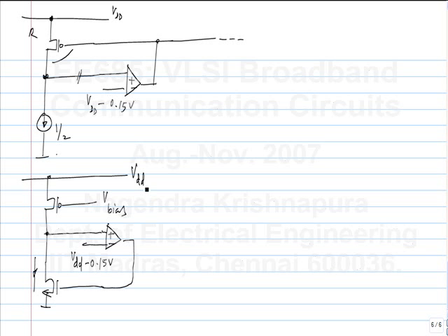So, basically you try to keep the swing constant, okay. You cannot control the I and R individually, but there is no need to control that perhaps. So, you try to keep the swing constant. Now, let us say there may be cases where I want to use a resistor, I do not want to use a PMOS transistor, and that could be because generally transistors can have more parasitics than resistors. I mean, that very much depends on how you implement the resistor, but one of the reasons is, so let us say this is the substrate of the chip, the transistor will look like this if it is a PMOS transistor.